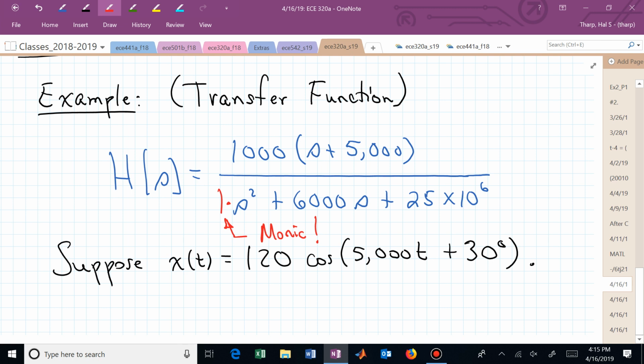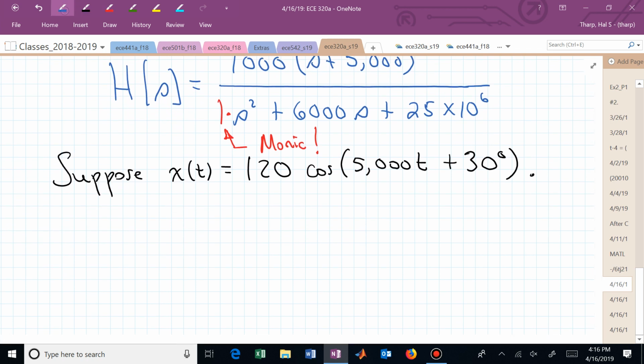If you've now normalized that quadratic to be monic, all you have to do to make sure, without going through the quadratic formula or plugging it into your calculator, is know: are both of these other 2 remaining coefficients present? Do they exist? And are they positive? In a future class, you can learn why that's true, but you could convince yourself with a few examples through the quadratic formula that as long as these 2 coefficients are present and positive, that polynomial has its roots in the left half plane. It has negative real parts. And that's the conclusion I'm going to make here.